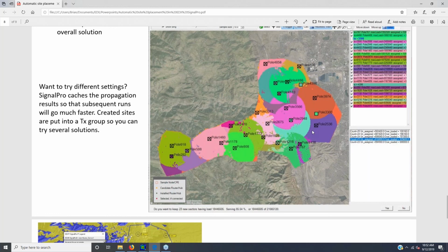I think so. One more that we just got in. Is it possible to set multiple sites at the same locations, but with varying heights or powers? Yes, you can. So the automatic site creation is going to always place gateway locations using the same site template. So the transmit power on the gateways is going to be the same for the purpose of gateway placement, no matter what. So it's really only selecting locations and not equipment for you.